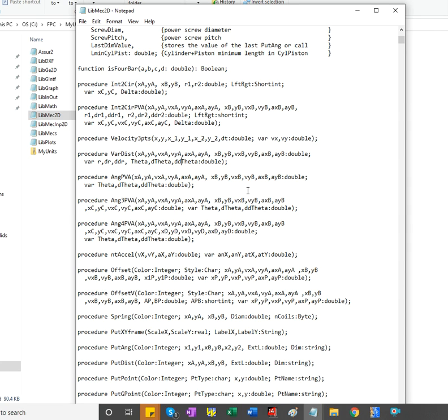Okay, so for example, I can have that crank rotating, and I can supply 0, 0, and 0, 0 as a ground point, and then the coordinates and their first and second time derivative of the endpoint of the crank, and it calculates for me. This will be, of course, the length of the crank, and 0. This does not change the length of the crank, but then it will be the angle and first and second time derivative extracted from knowledge of the 2 points.